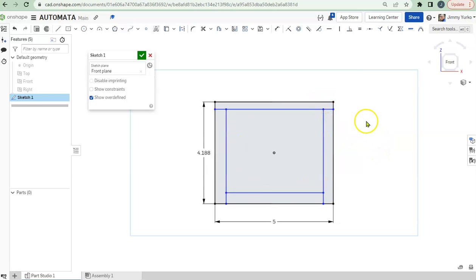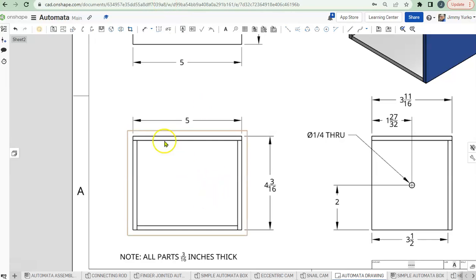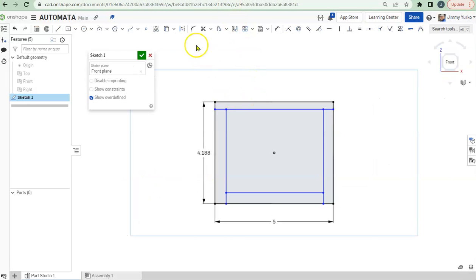This is the shape that we want. Just like that. So this top board is the longest, the bottom board is the shortest, and the side boards are the mediumest. We're going to go ahead and apply the dimension to it now. Either tap the D key on your keyboard or go up and hit the dimension. Well, remember we're dimensioning between two lines, so you click both lines that you would like to dimension the distance between. And it's 3/16 thick